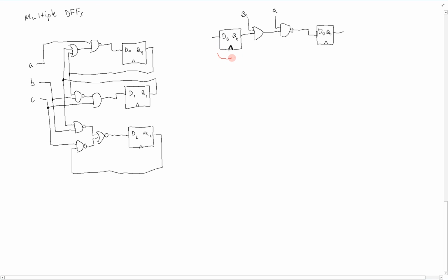We look at the propagation through the flip-flop, so TP-CQ, then through all of the logic, TP. In this case, if we're trying to find the minimum clock period, then it's going to be TP max. And we're again back at the input here where we have to obey that setup time constraint.